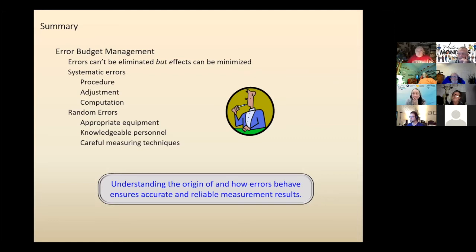That's one of the problems students have when they first start learning surveying: learning the processes that help them control the errors. So that when they do get a good traverse closure, they get it by design, not by accident. You don't want to keep your eyes closed and hope it turns out well when you get to the end.